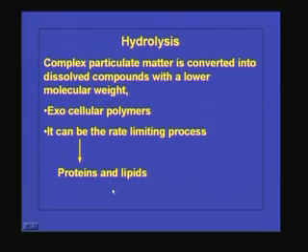So first we will see what is happening in the hydrolysis process. We know that the treatment of any wastewater takes place because of microbial metabolic activity. How does the metabolic activity take place? The substrate has to attach to the cell and penetrate it, and inside the cell the metabolic activity takes place. But most of the organic molecules present in the wastewater are very large in size, so they will not be able to penetrate through the cell membrane. So how can the cell take in this organic matter?